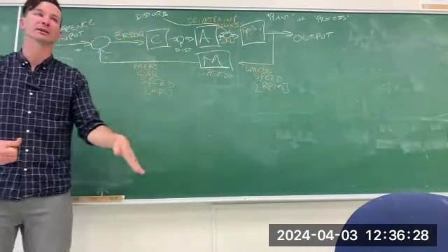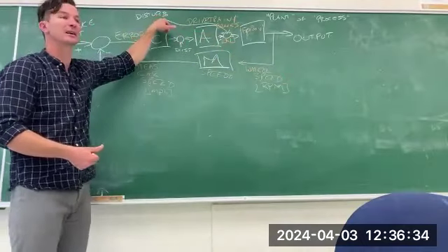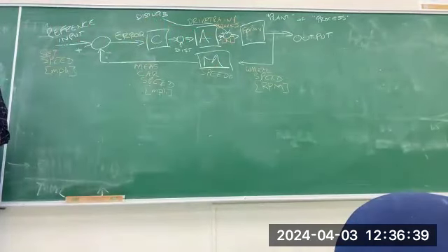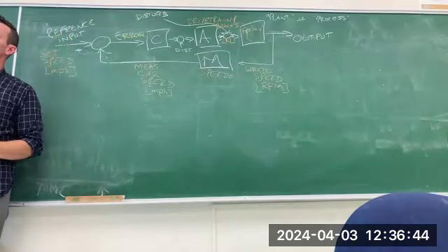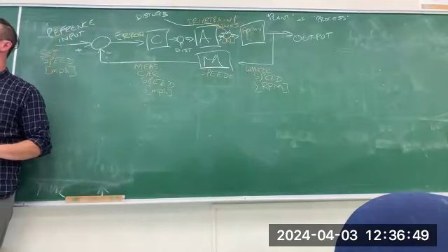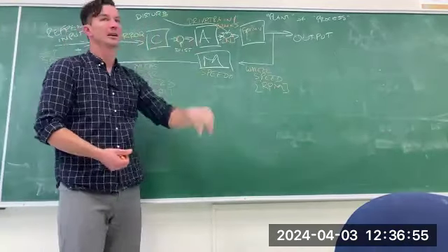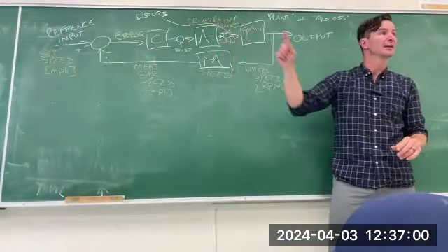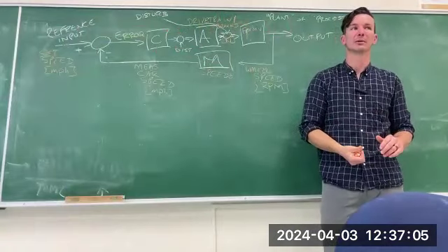If the hill is tall or the hill is steep, we want the car to keep a fixed speed regardless of the size and the severity of this disturbance. Okay. Can you imagine how we want to react differently to changes in set speed versus changes in disturbance? That's actually the heart of what makes controls, especially classical controls, difficult. If we model a step change here versus a step change there, it's all in a loop. So you've got to be careful about over designing for one and under designing for the other. This is all stuff we'll get into more throughout the quarter.